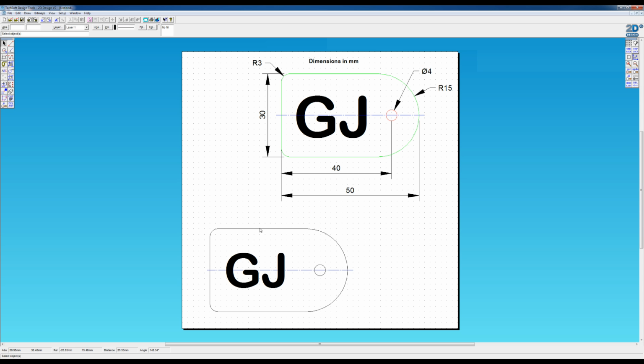If we're going to change the whole perimeter, one way we can do this is by right clicking on a line, right click on another line, right click on another line, and work our way all the way around. Sometimes it's easier selecting everything, so we're dragging a box over everything, and simply right click to deselect.